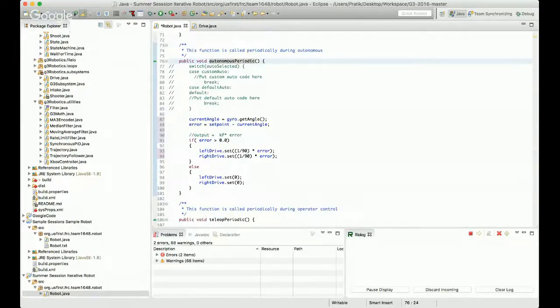It ends up being really good because there's a lot of friction with the drivetrain and turning. There is a decent amount of scrub. So any amount of control where you're trying to slow down as you reach your target ends up being plenty to stop on a dime.